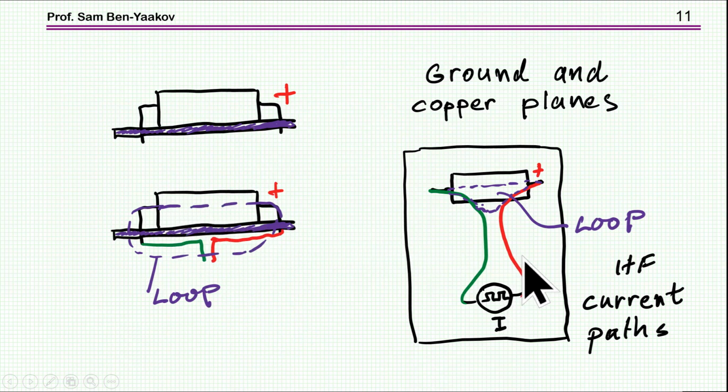Same thing goes if you have a PCB with layers of plus and minus, and here I'm showing the source of a ripple current. In the layers themselves, the lines might get together at high frequency. They are getting close to one another, the current flow here. But eventually they'll have to split here and get to these points, and therefore you end up with this loop here no matter what you do.